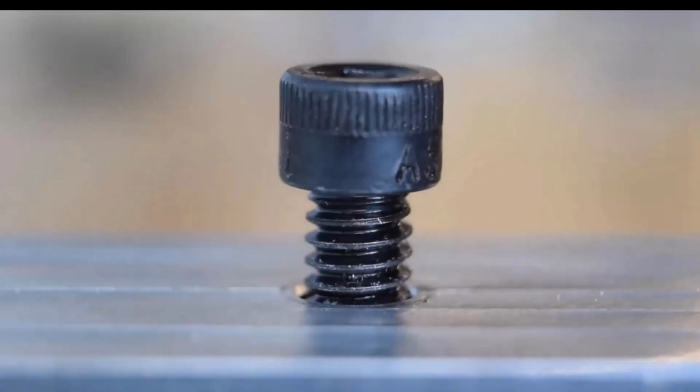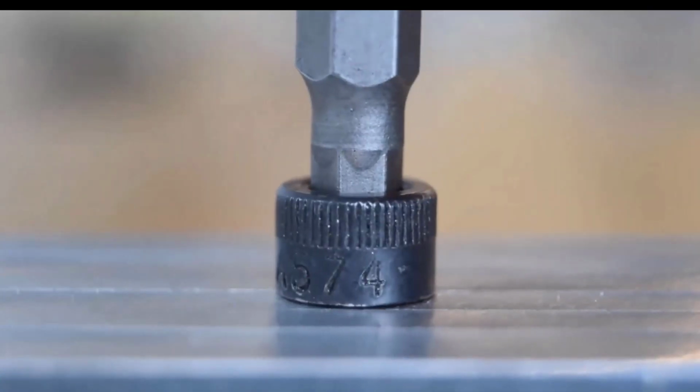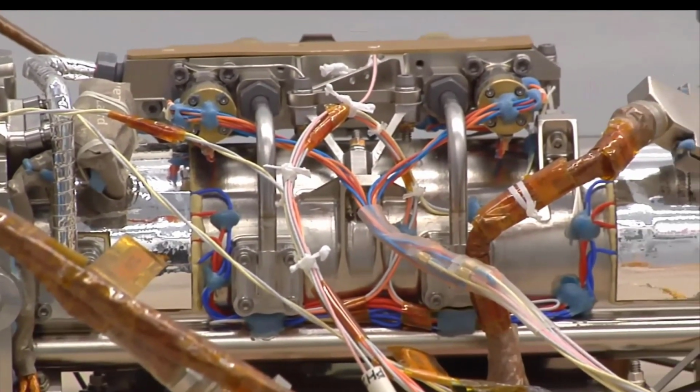The only trouble with this method is that most of the applied torque is lost due to friction in the threads and between the head of the screw and the workpiece. The materials, coatings, and lubricants all play a role, and a correction factor, called the K factor, is used in the torque formula to account for this. However, even when the K factor is chosen correctly, the torque method is only accurate to within plus or minus 25%. For statically loaded joints, there's no reason not to apply the maximum preload to the fastener.